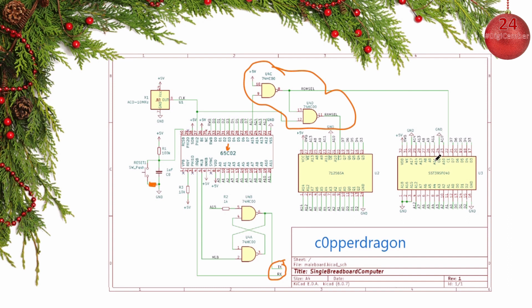And they don't have any mumbo jumbo, as I said, about the Phi2 clock and read-write signal on this bus. They don't seem to care at all about the read-write state of this as they only use the chip enable and output select of these chips. Maybe that's okay, I'm not totally sure.